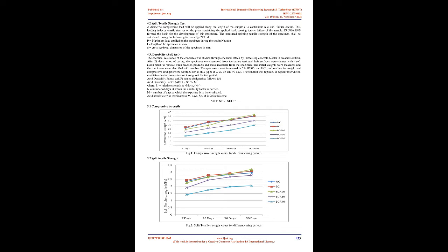Bacteria precipitate calcium carbonate, calcite, CaCO3. The physical and mechanical properties of calcite are closely similar to those of hardened concrete, and hence it can be used as a crack-filling agent for concrete structures. It is produced biologically and does not possess any harmful chemicals. Also, its production is self-sustained, happens without any human support, and has the potential to remediate every minute crack. These properties of calcite make it a perfect filling material for cracks developed in concrete.